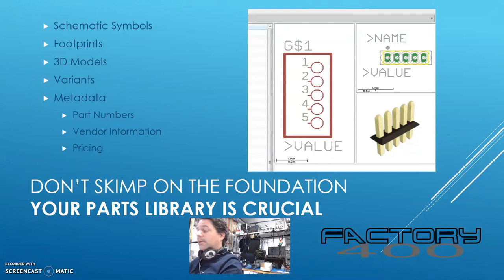Well, in my case, I need to keep track of part numbers, and when I finish a schematic, I want to have access to the DigiKey part numbers and the manufacturing part numbers that I used when I was designing the circuit, so that when I go to lay out the circuit board itself, I can cross-check and verify that everything is looking good and I got the pins right and all of those kinds of things. So I'll put a DigiKey number in there. I like to put pricing on, at least on the expensive pieces and parts, so that I can more easily keep track of how much my design is going to cost.